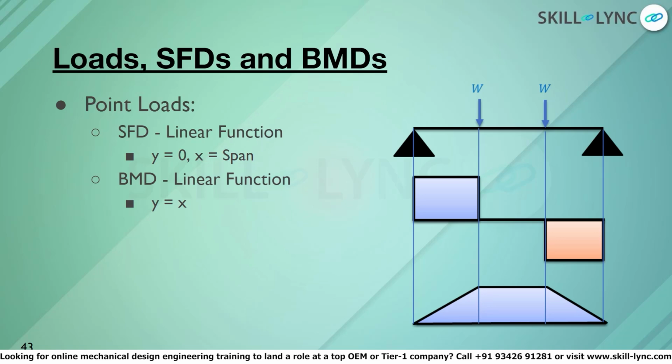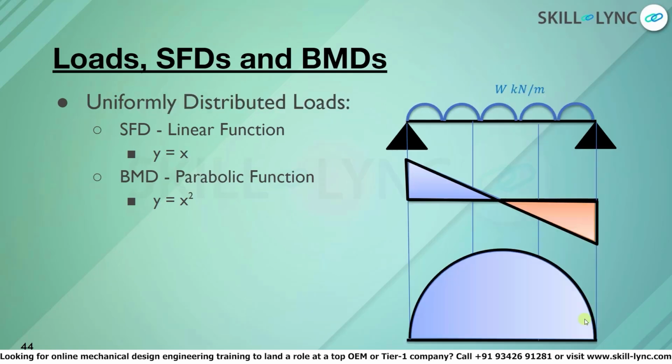While the BMD is also a linear function where y is equal to x, that is shown in the second figure, where we have the y value equivalent to the x value, which is the span. This is exactly why in this figure our BMD plot has a tilt which is equal in both the regions.